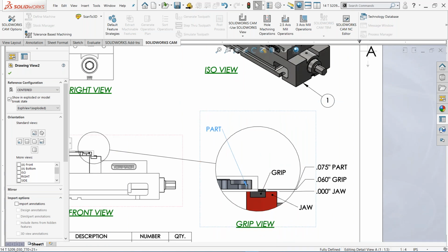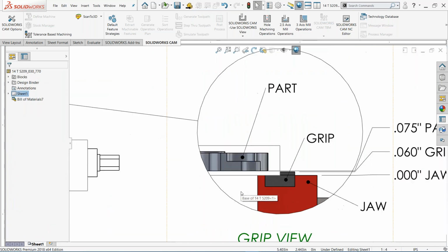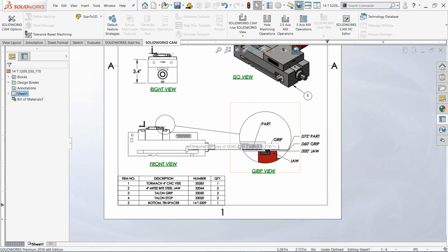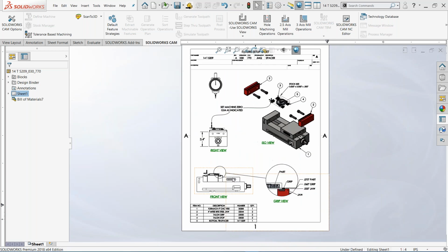So what we're doing is we're actually using Mighty Bite's tail-on grips. They're really, really cool. And what they allow us to do is to grip just on a tiny amount of that stock and actually have the part ride just above that, so that we can machine on all 3 sides at once. Great functionality and very easy to use.